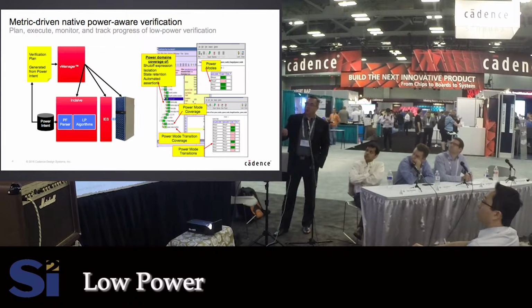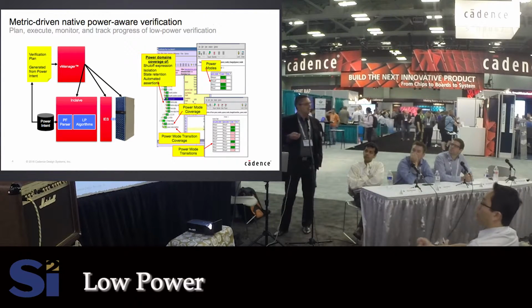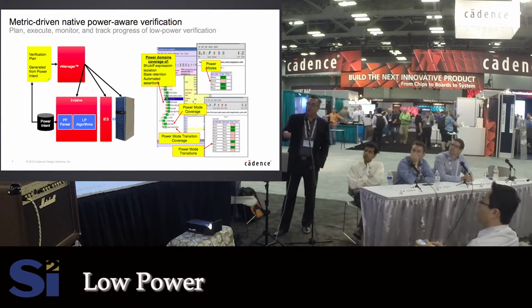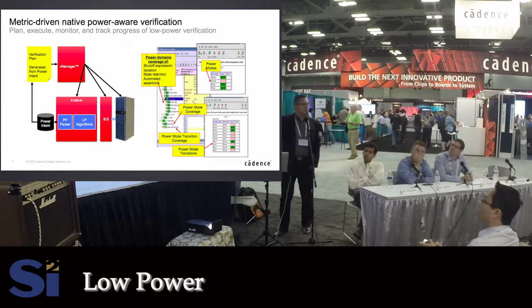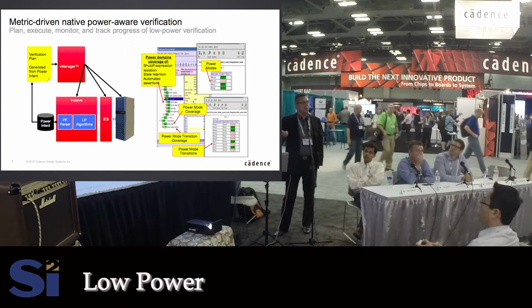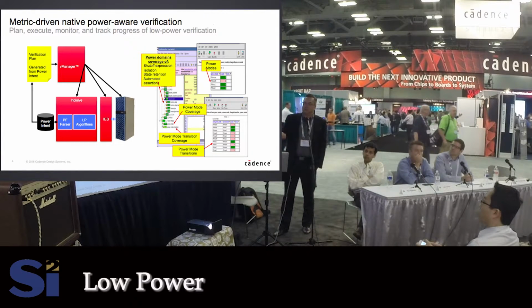If you look into metric-driven, power metric-driven verification, what people are doing today is they will look at shut-off and take the power intent as it is standardized with CPF, UPF, and will drive it into Incisive things like RTL simulation and into emulation, and they will essentially figure out how to verify the different power modes, the different scenarios.